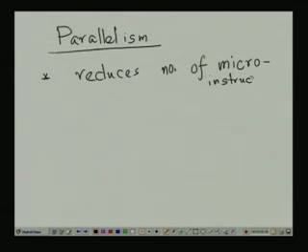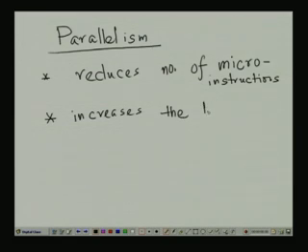Obviously, the microprogram is much shorter than if we consider all the micro operations separately, but it increases the length. Obviously, as a number of operations are combined, though it now gets a common opcode, the length of the micro instruction is increased.